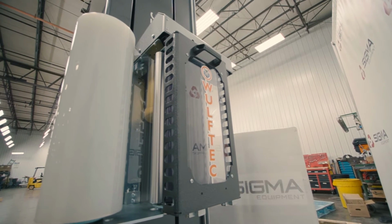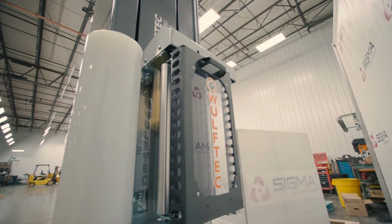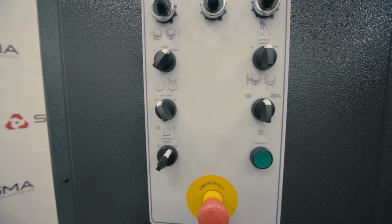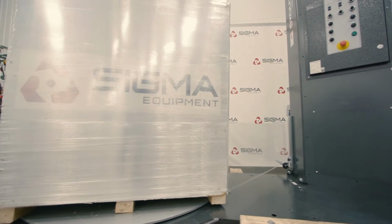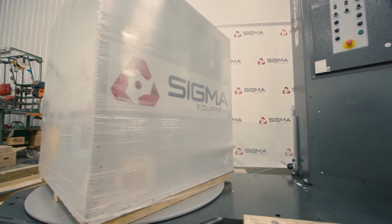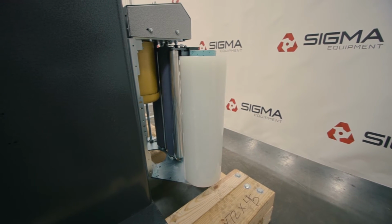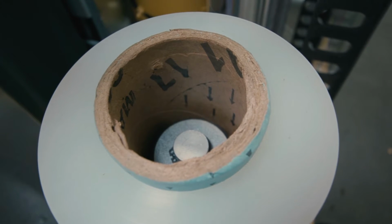The operator has the option to manually move the carriage up or down if they would like to focus on specific areas of the product to wrap more or less. The rotation of the skid or pallet can also be set to manual. This can be beneficial when placing product labels on each side of the wrapped product for identification purposes. The wrapping process starts by loading the film on the film reel, making sure that the arrows in the core are pointed down.